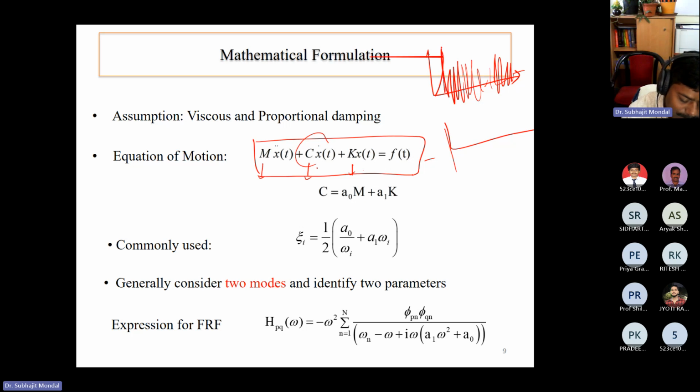This part may go up and down, but for the rest of the cases, if we consider the mass and stiffness case, you'll observe that changes in this response will be very similar in nature. So what happens if you do the testing in the time domain? You will observe it is very difficult to identify which parameter is causing the change in the response.